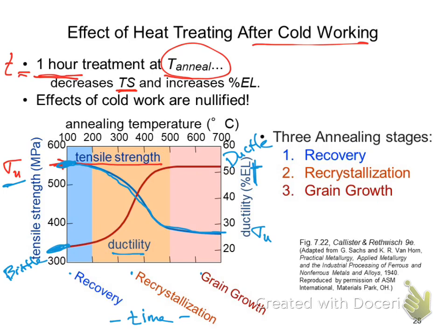because we have to do something to the material to create that shape, whether it's cutting or welding or punching or those other cold working type manufacturing processes, we end up with these particular changes in the material from what we had originally picked. And the cool part is that after you've done your manufacturing, you can put it back in the oven and anneal it, and you can regain the initial properties that you wanted. So that's where we say the effects of cold work are nullified.